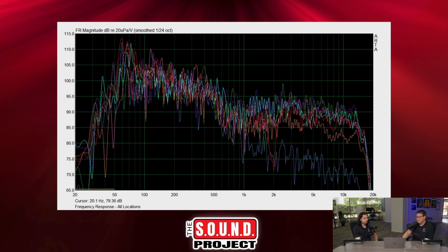This looks like there's a lot of information going on here. This is every location that we showed previously, with the frequency response overlaid. We look at patterns with this, to see what the front of house looks like versus audience locations, because sometimes there are discrepancies there. It's important to know that if the front of house engineer has a dip at a frequency and it's a peak everywhere else, they shouldn't be boosting that frequency, because it's just how that particular location hears. But it's nice to be able to see this.